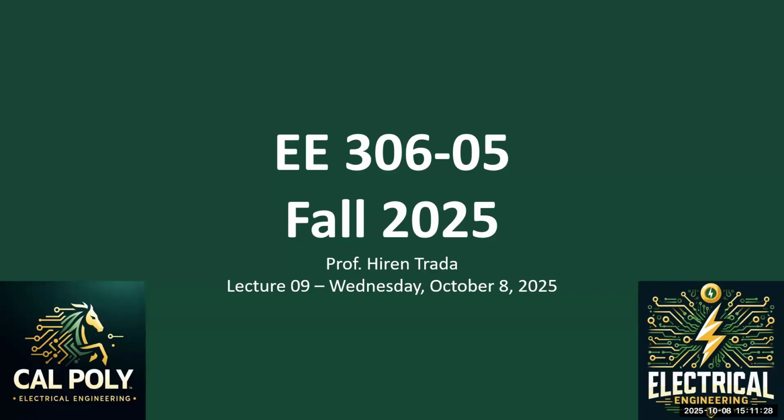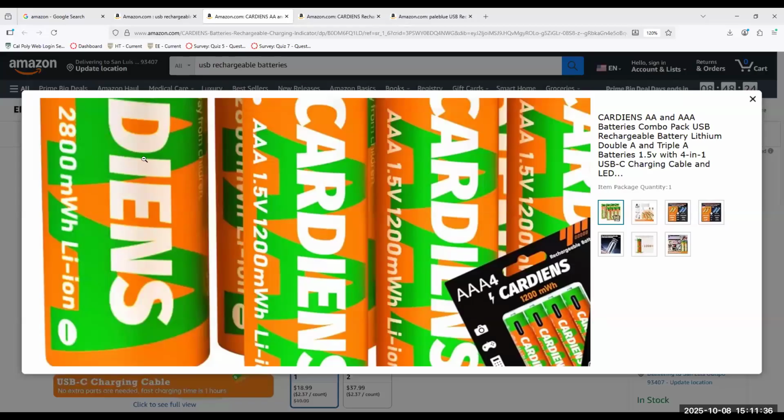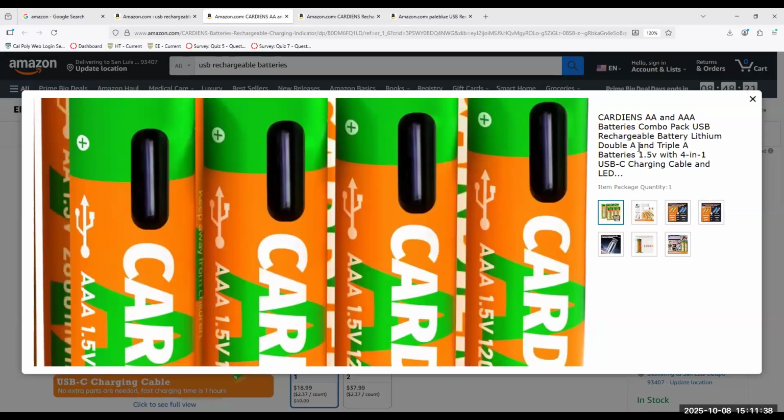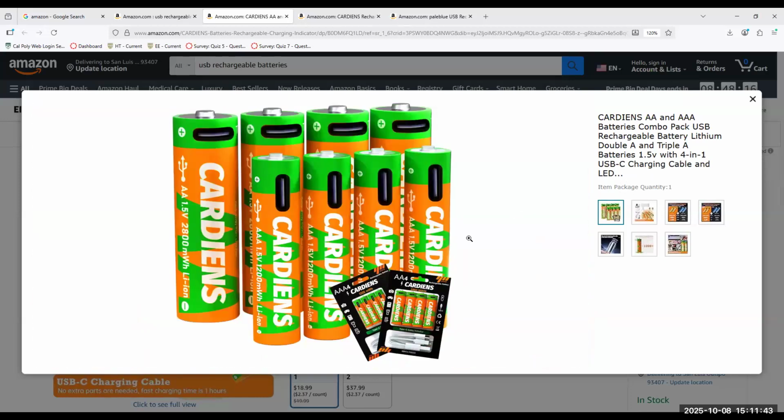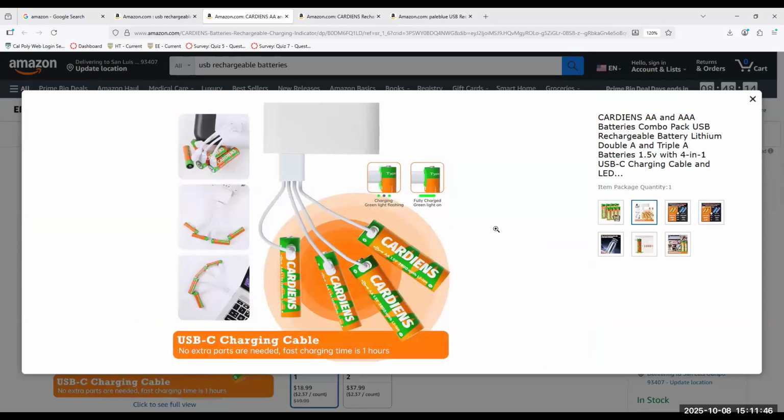We'll begin. Oh, not that window. Oh, but since I bring up the window, this is something we were talking about in the previous class, voltage, power delivery between like four different power outlets. How many of you have seen this before? These have been available in the market for a long time. So we were discussing connecting loads in parallel. So this was a real life example that I brought up, that you can have multiple loads connected in parallel to the same voltage source and what it does to the power rating and the requirement.